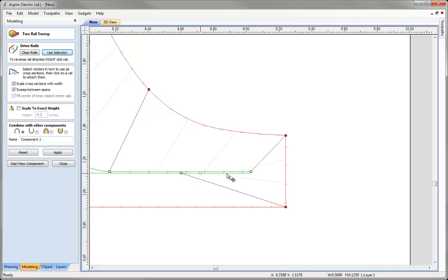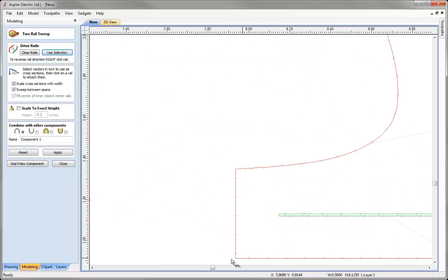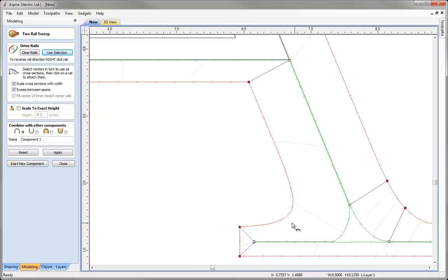Again, snapping to the corner, using the cursor and seeing the snap positions being indicated. Then every time you see me zoom out there, I'm just hitting the F key on the keyboard to zoom everything back into the full view. So F, and then the last one if we want to add a bit more control again around the curve. Really up to me as to what I want to do there. So that should now close up nicely.